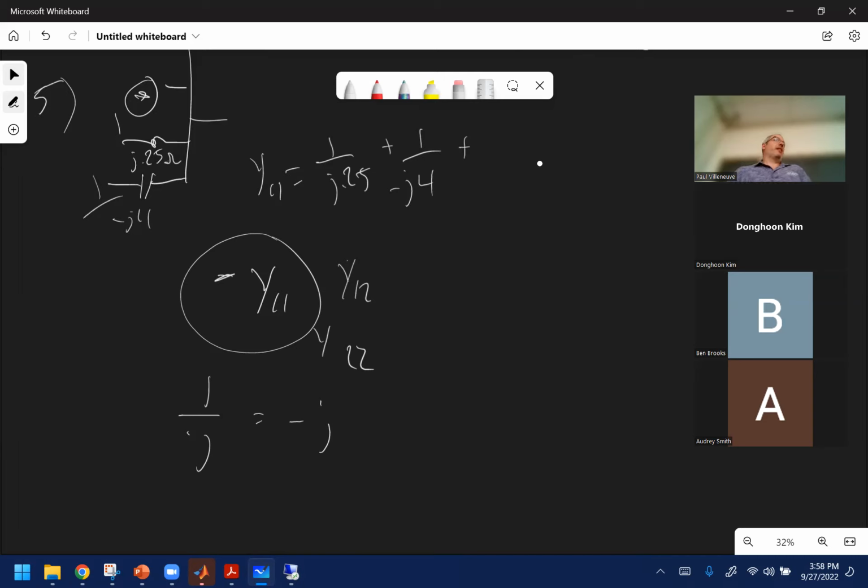Maybe. It depends on your work. I don't know what I did wrong, so I just changed them all positive. Because you might not have done the J terms. You've got to be careful, because a capacitor is minus J4 but is only positive J.25. So when you add things, you've got to be careful about adding and making sure you have the J terms correct.